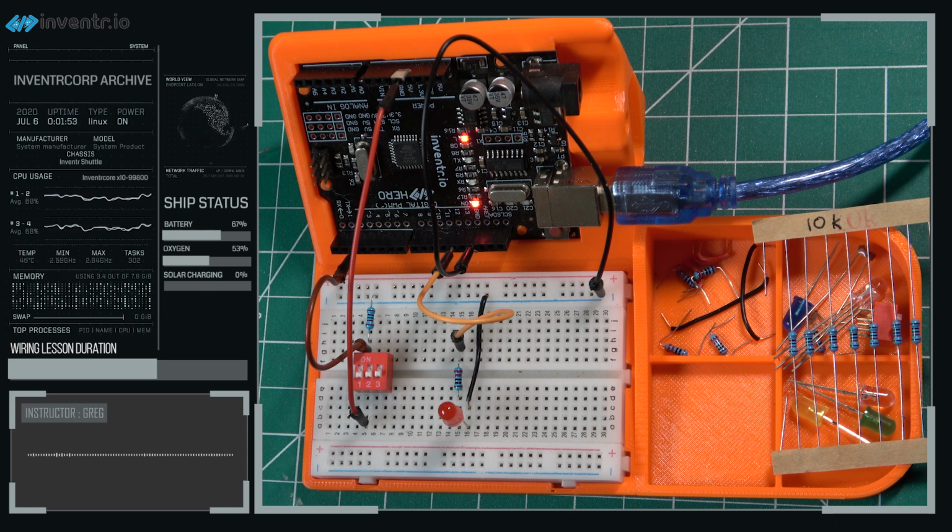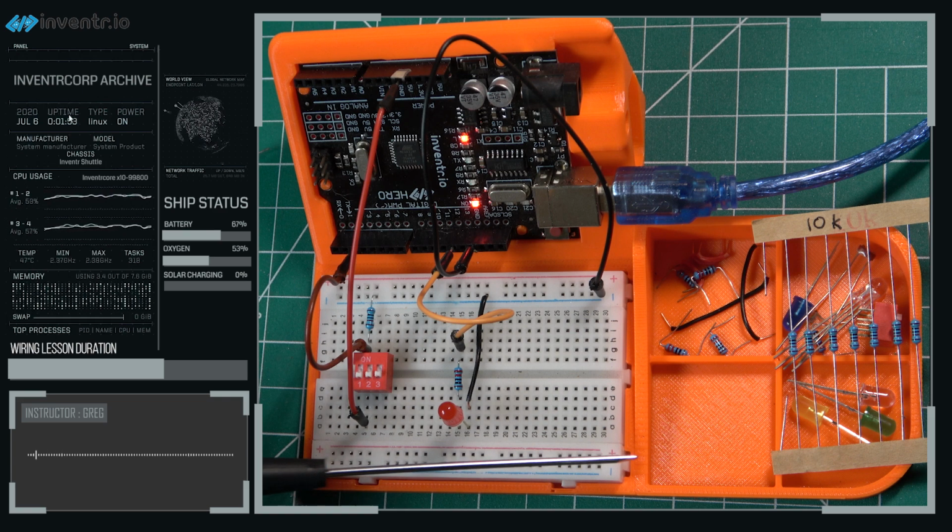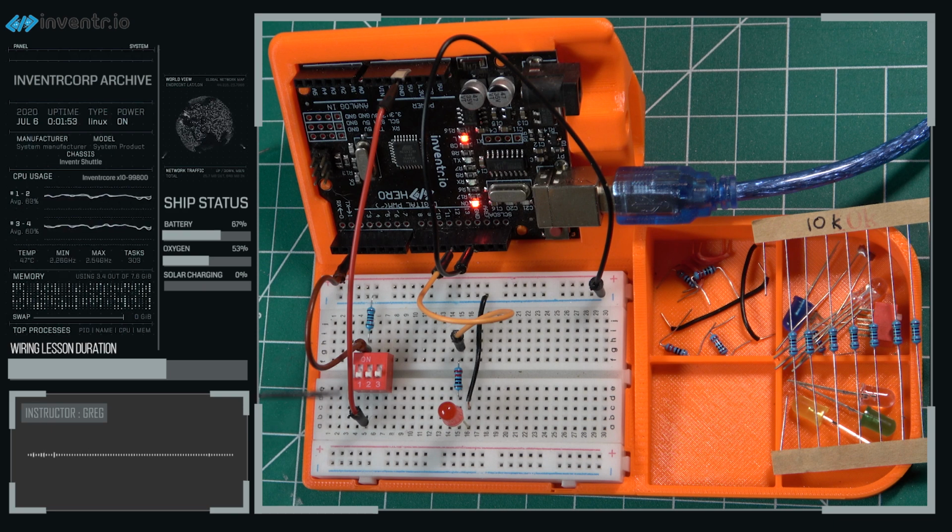You'll notice that the two rows along the top side and also along the bottom side of the breadboard are labeled with red and blue lines, and they're special because they are connected horizontally all the way across rather than vertically like the columns in the main part of the breadboard. And since they do connect horizontally all the way across, they provide convenient access to any components that may need to access them from the main part of the breadboard.